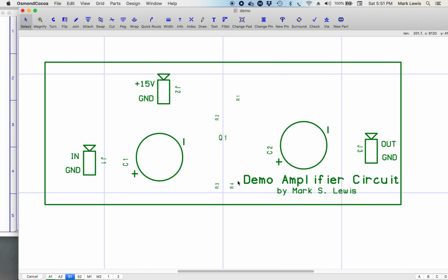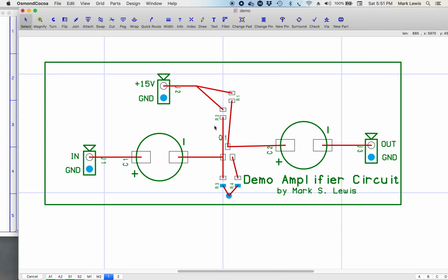And then usually you can specify, most of the time it's white text. So they use white ink so it stands out on the circuit board. Some places might have others, but in general, unless you're making a white circuit board, the white ink stands out best and you can actually read things. And clarity is important because when you start getting to really, really small parts, and these aren't the smallest parts you can get, you can get some parts much smaller, it would be hard to read the text.